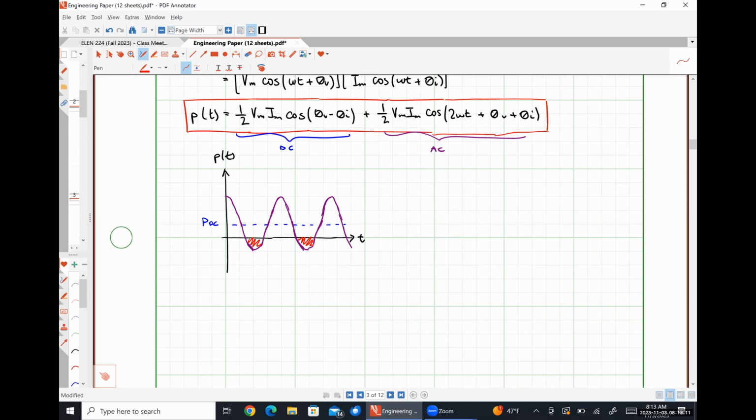So at some point in the interval here, or actually multiple points in the interval here, our black box AC network actually winds up supplying power back to the source that is exciting. So our network, for very brief intervals of time, is behaving like it's the source, and our supply is actually acting as the load in this system. And we can see that by the sign on the power over these particular parts.